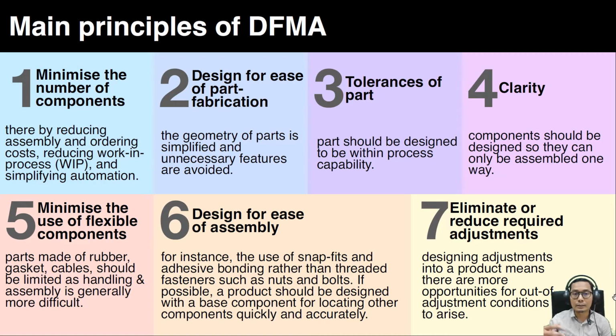And then the sixth principle is to design for ease of assembly. For instance, to design a part or a product that could ease the assembly process, use snap fits and adhesive bonding rather than threaded fasteners such as nuts and bolts. So it's better to use snap fits or adhesive bonding, and if possible, a product should be designed with a base component for locating the other components quickly and accurately.